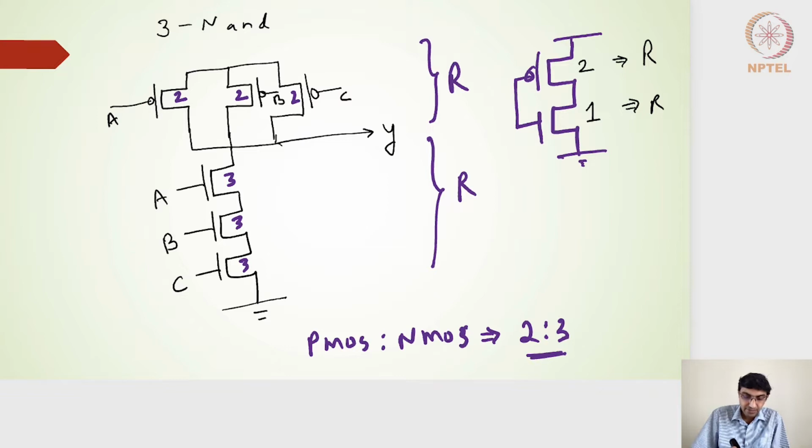We also estimated the delay by expressing the capacitance at the output node and at the internode diffusion nodes. At the output, I represent the accumulated capacitance from the diffusions of transistors A, B and C on the PMOS side, and transistor A on the NMOS side.